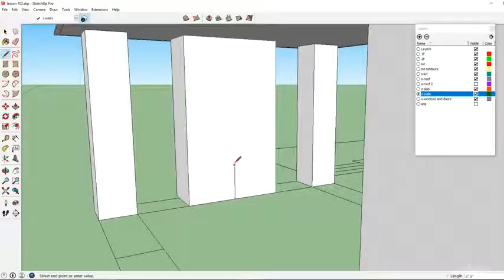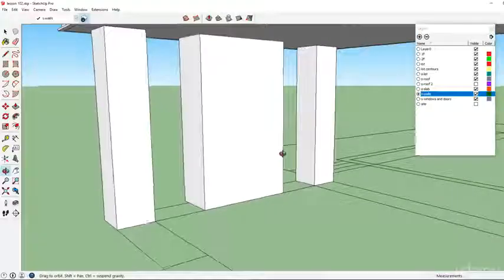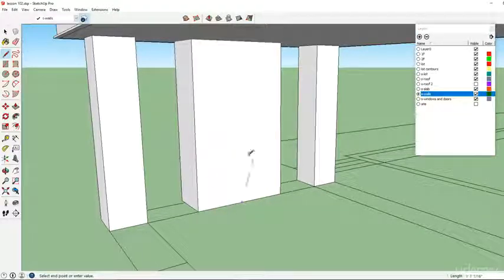And now let's create a fireplace area. Let's type 36 inches, and I want to create just a horizontal fireplace that's 16 inches long by 4 feet wide. Go down 16 inches, and let's go ahead and push that in.